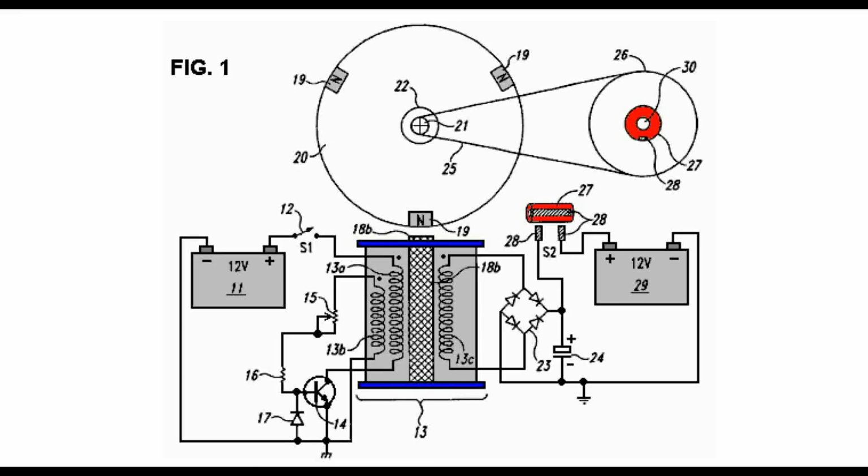However, the switch 12 might be a solid-state switching circuit, a magnetic reed switch, a commutator, an optical switch, a Hall effect switch, or any other conventional transistor or mechanical switch. Coil 13 is comprised of the three windings: power coil winding 13A, trigger coil winding 13B, and recovery coil winding 13C. However, the number of windings can be more or fewer than 3 depending upon the size of the coil 13, size of the motor and amount of available energy to be captured, stored and used as measured in watts.